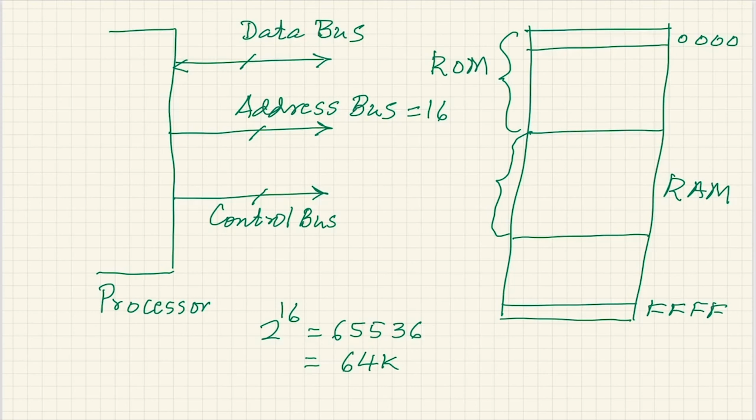right. So, it is going to use a unified bus to read the program from the ROM and read and write variables and store variables in the RAM. What is the problem with this? What are the characteristics of this architecture? It is very simple. The number of pins required by the microprocessor to connect to memory devices is the lowest that you can find. But there is a little problem in this approach in terms of the number of activities that it can do. Because there is only one common bus, you can either read the memory contents or you can write to it. You cannot do both things.